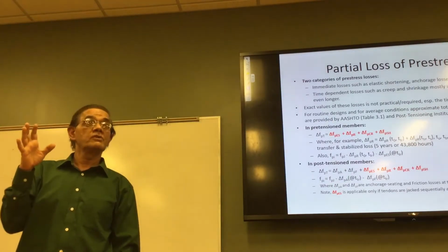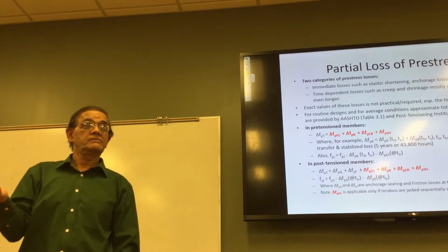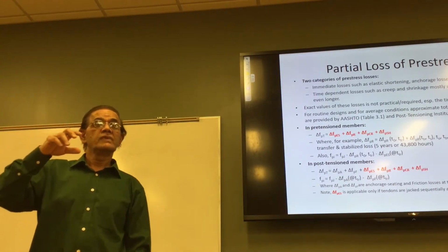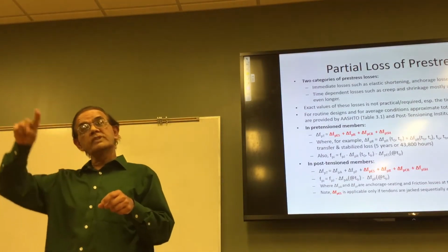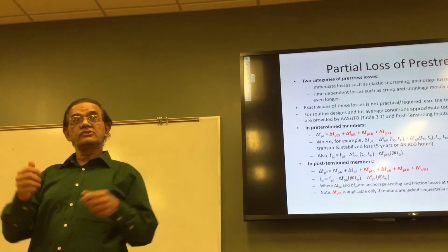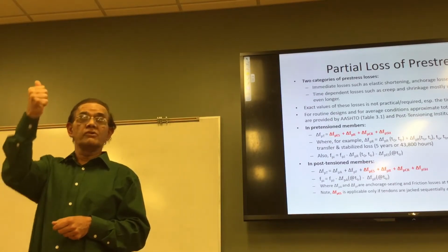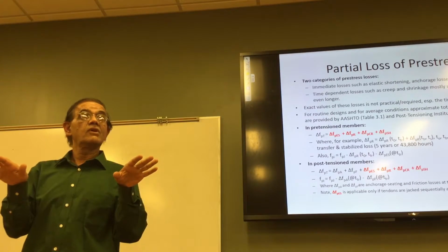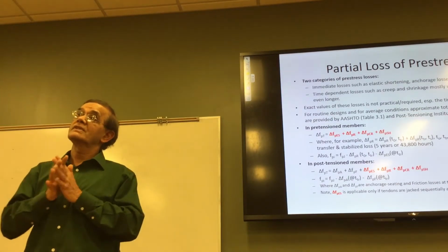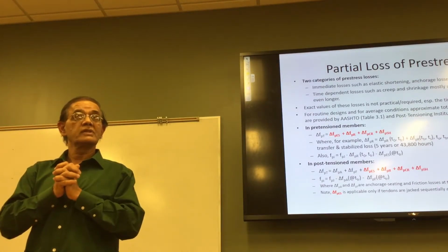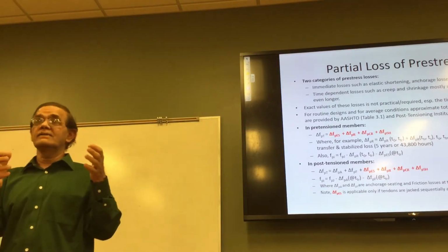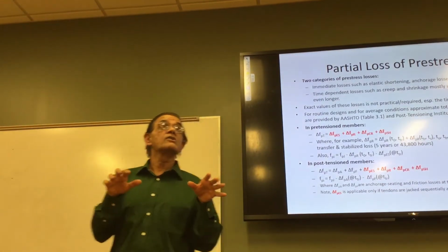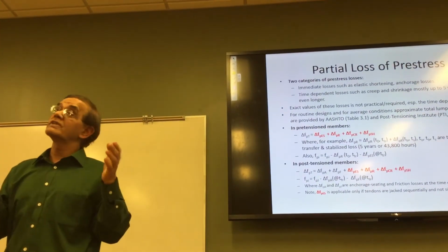The friction, if you remember, is a function of normal force and the type of material. As you go through this shape and you try to stretch, you're going to push against it, so there is a normal force. And depending on the texture of the material, how rough it is, you will get bigger and bigger friction. So you're pulling something and the friction points, the extreme points, top and bottom, are going to say, no, you're going to drag here, so I'm going to reduce you.